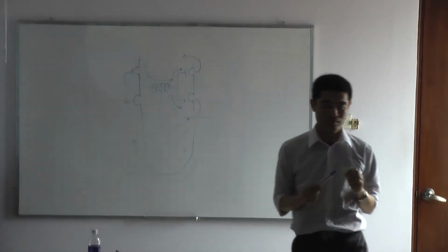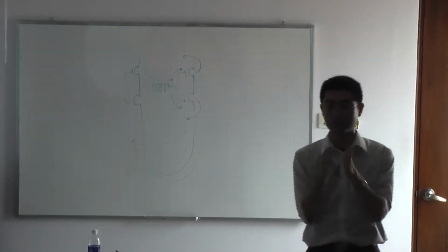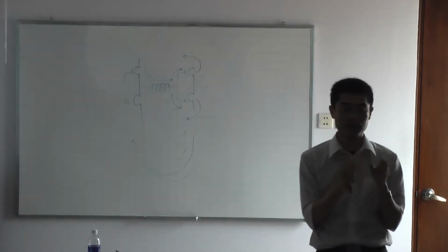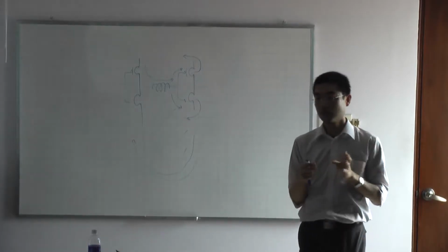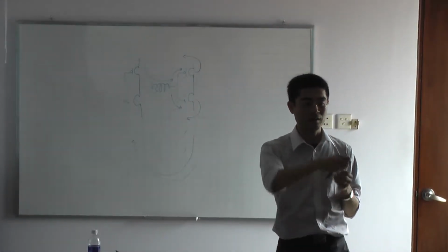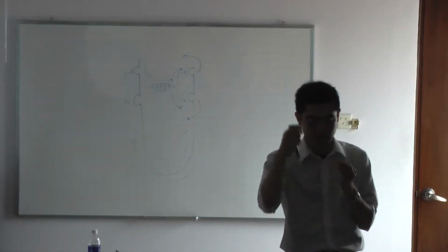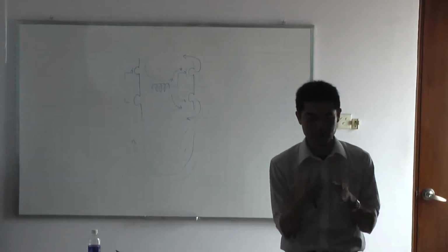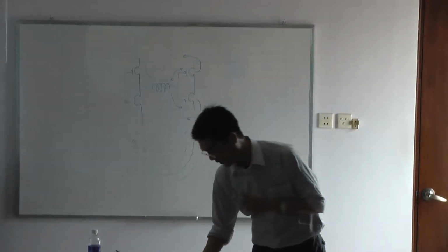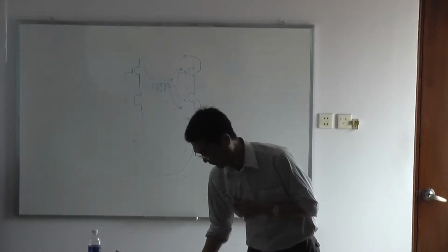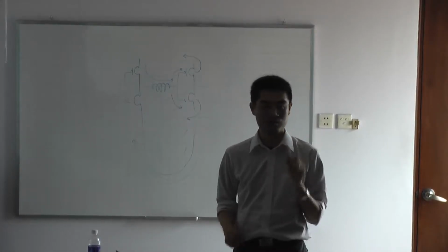So the point here is that we have to take care of the return path. The loop area should be small in order to reduce the inductance. Otherwise, you will have inductance, and it will degrade the delay and the performance and induce noise. Once you suffer from inductance, check if there is a large loop. For your measurement, always take care of how the signal returns and make the loop area as small as possible. And that's it, return path 5. L is proportional to area, so we have to reduce the area as small as possible.